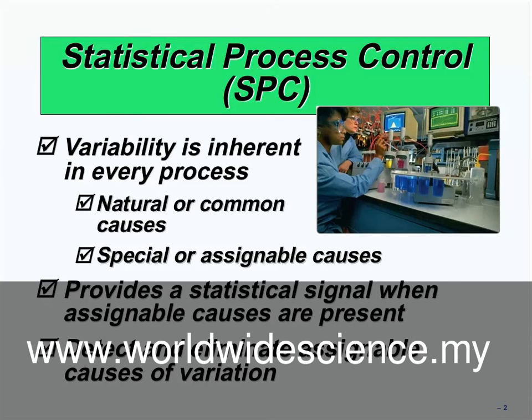For control of the process of production, or for considering the quality of the production, there are some methods that the operation manager can use. They should use samples, for example, at a specific time. For example, every 1 hour, or every half an hour, they should choose a sample from the production and check them to see whether they are defective or have a problem or not. If they have no problem, they can continue the process of production.